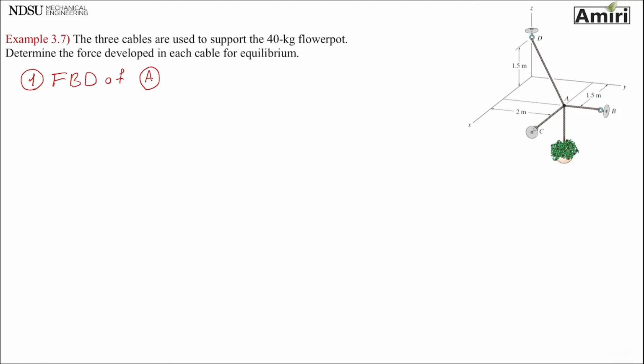So in 3D way, it's exactly the same. The steps are exactly the same as a 2D free body diagram. Step one is isolate and draw outline of your shape. Step two is to put active forces, the forces that are trying to mess up the equilibrium. Here I can see weight.